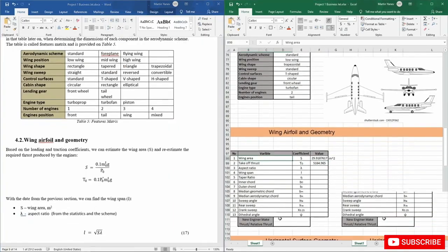And I actually found the engines, you can also research them. I found a more powerful engine, which is the Honeywell F124 J100, and two of these engines will produce 5,220 daN, and also their relative thrust is 0.36, which is now acceptable for our needs. So we're going to change the engines to these ones. And this is normal when you are designing an aircraft, to constantly change the variables of the aircraft with every next step.